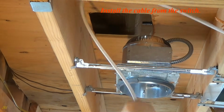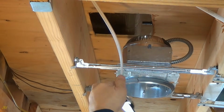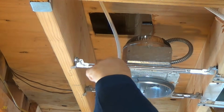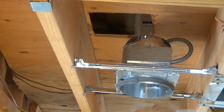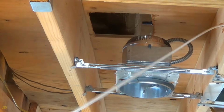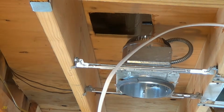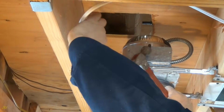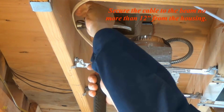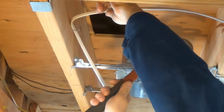Install the cable from the switch. Secure the cable to the beam no more than 12 inches from the housing.